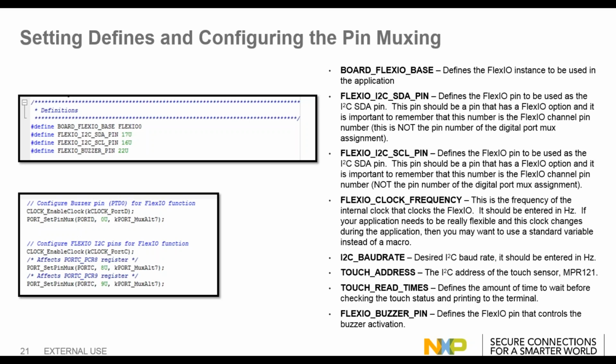So again, here you can see at the top the configuration for port D0 and at the bottom the configuration for port C. So physical connections that get enabled by software, these are very important aspects of this demo, understanding where the FlexIO pins are physically connected to, which ones are being used, but leveraging the software that we have in place greatly reduces the complexity of doing this.